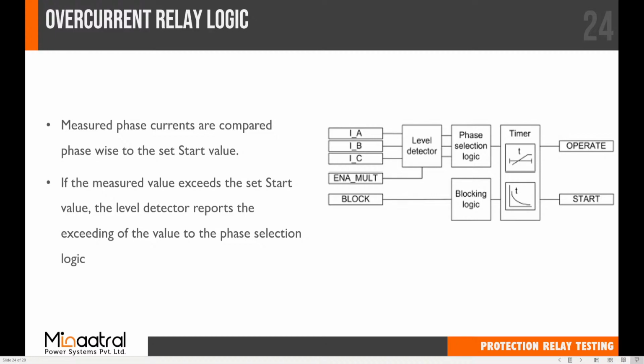So what we have done is we are injecting current from your Omicron, right? And we are measuring what is going to be the pickup value, right? At what point does the relay pick up, and at what point does my relay operate?